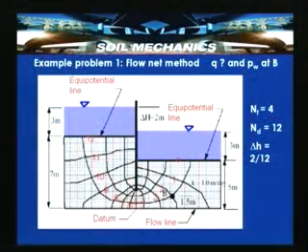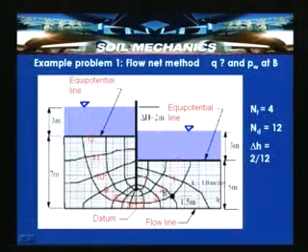Now, the structure is drawn on graph paper as represented here: 7 meters is the depth here, and 3 meters here and 3 meters here, and it is embedded into the ground here. Now let us draw the flow net. In constructing flow nets, first the approximate flow net has to be constructed, and then it has to be checked that the flow net does not intersect the impervious boundaries. You cannot draw a flow net which cuts the impervious boundary.